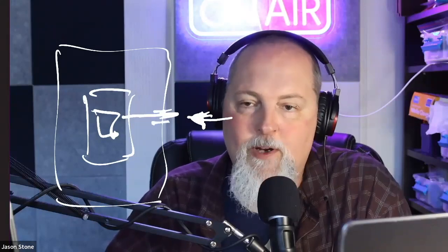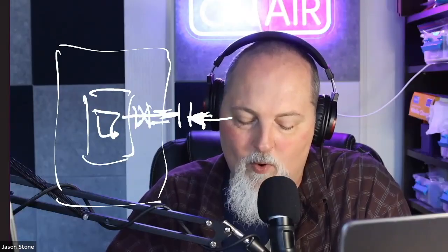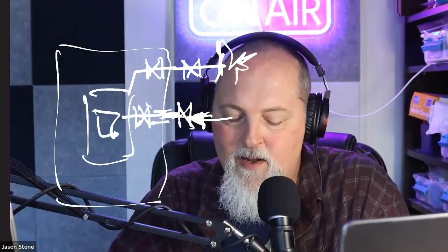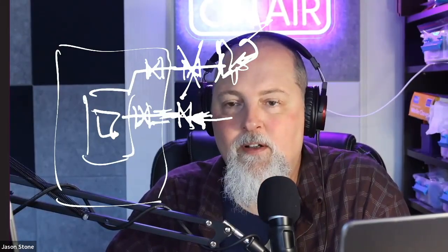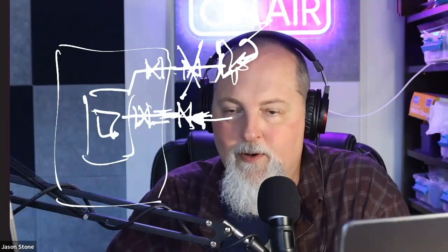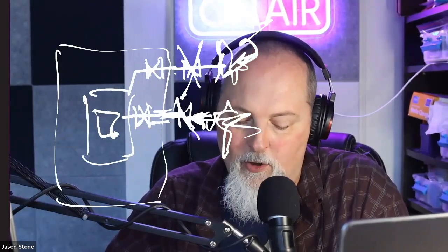What we do is put isolation valves before and after these penetrations. Steam has to come out of the reactor, so I put an isolation valve before and after that penetration so that we can isolate a leak. If the steam system breaks right here and all this steam starts escaping, we can close this valve and isolate it so we don't lose our inventory. If we have a reactor feed water rupture, we can close this valve.